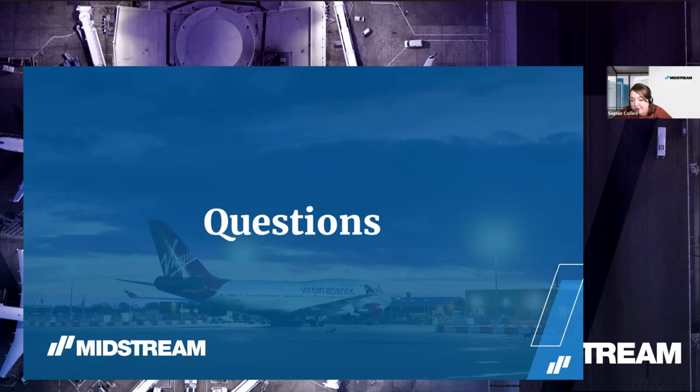Okay, fantastic. Our next question: are there any cons to using 5,700 Kelvin compared to 5,000 for the entire apron? I just think it's too blue. It's just an uncomfortable light. It feels a little bit like you are under some kind of, it's just not very natural. 5,000 is much closer to natural daylight. So 5,700 is just blue, and it feels kind of cheap or cool, an unpleasant feeling. So the only cons are the perception, I think.